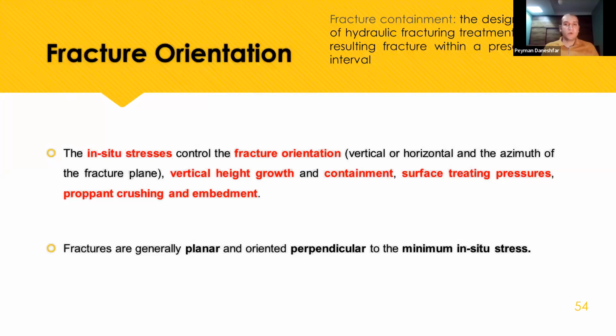The fracture orientation, vertical or horizontal, and the azimuth of the fracture plane, vertical height of growth and containment, surface treating pressure, proppant crushing, and embedment. Fractures are generally planar and oriented perpendicular to the minimum in-situ stress, and parallel to the maximum.